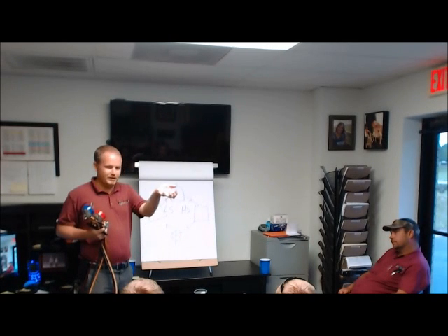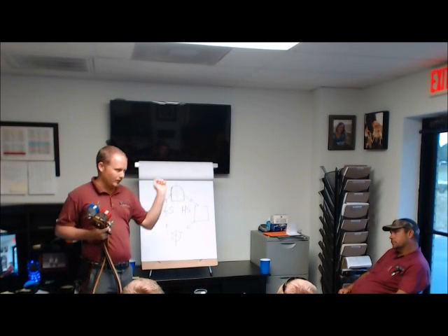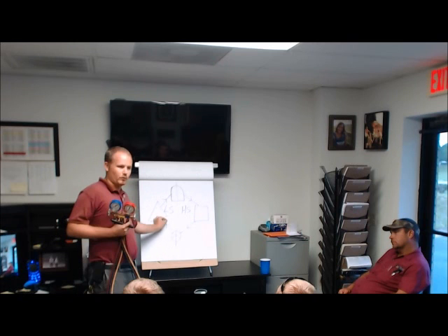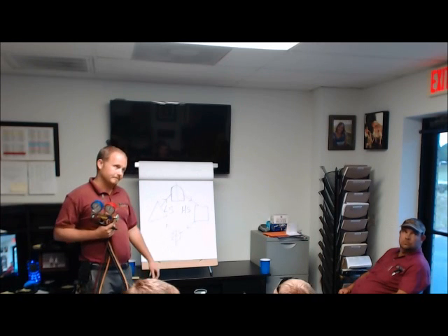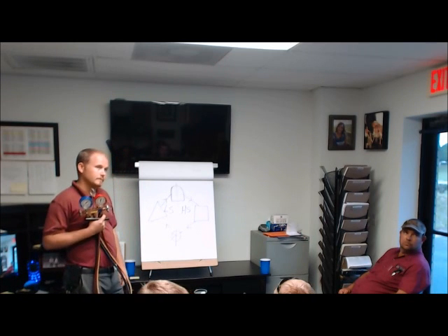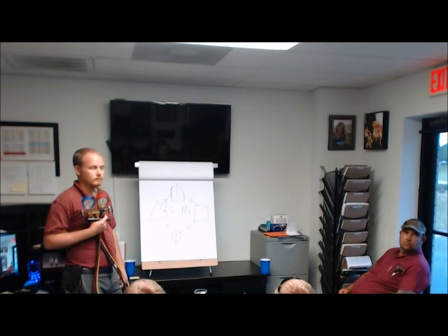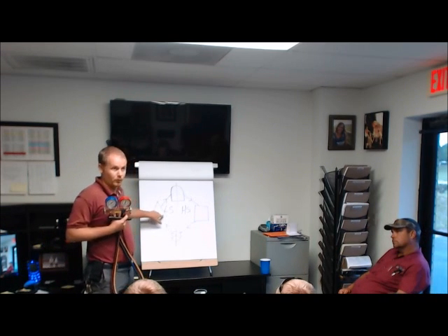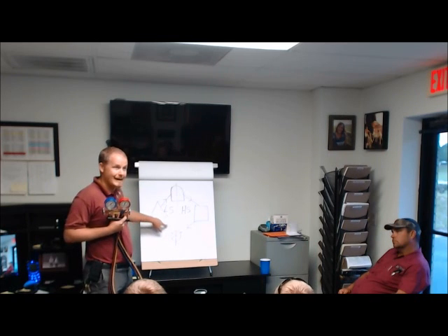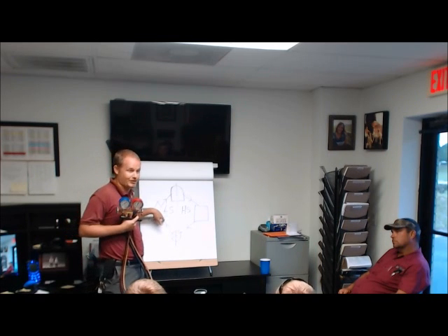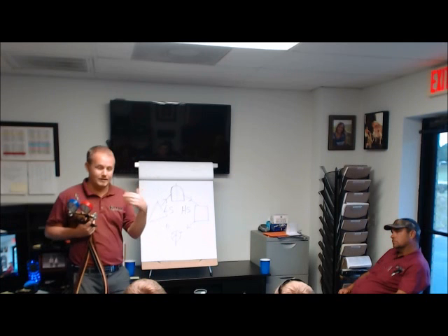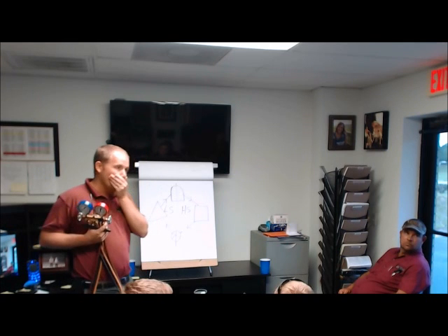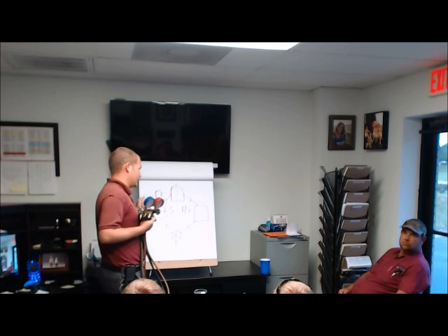You have your expansion valve that's mounted pretty much right on that evaporator coil. Really, these two are kind of married into one almost. Well, isn't the evap coil your expansion line because you're expanding through the evaporator coil? It is. This really becomes an extension of the evaporator coil, because the state of refrigerant in this is what we call flash gas, meaning it's in the process of boiling off. And it should be that way pretty much from there straight throughout the evap. Correct, pretty much, yeah.